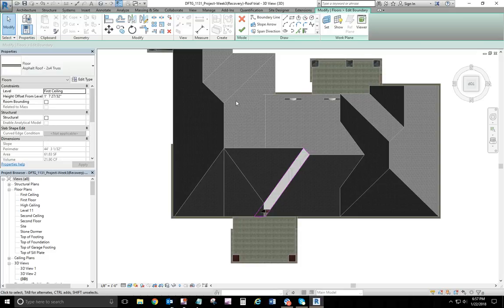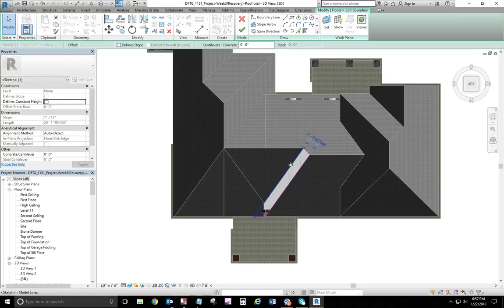I had turned this one off and created another roof, this little piece right here, that didn't go all the way over and join, but I made sure that the levels on the front were equal, okay? And that created my ridge line here. And so I did these two lines, and they are at 125 degrees from the backside coming around. Okay, I didn't worry too much about the dimension across this way. I just wanted the angles to be the same.